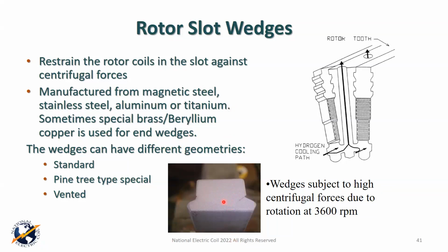One of the things you should know about maintenance, and I know there was a question early on about flux probe testing: flux probe testing is basically an electrical test that you can do in a high-speed balance pit, or you can instrument your generator to monitor it, and it looks for turn shorts between the turns inside the copper conductor of the rotor coils, all right? It's a great test. It's a great device, both in the high-speed balance pit and in operation. It's a very specific test. It doesn't do anything but that, okay?